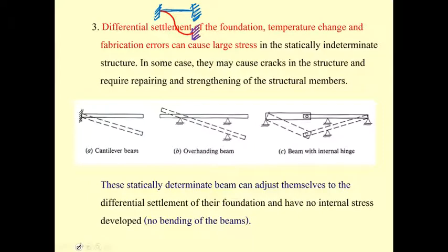Now what would occur if you pick up the ruler loosely, and then you move one of your hands downward here, you may see your structure can change the shape easily without bending. Since it can move without bending like this, there is no shear, no normal force, and no moment.